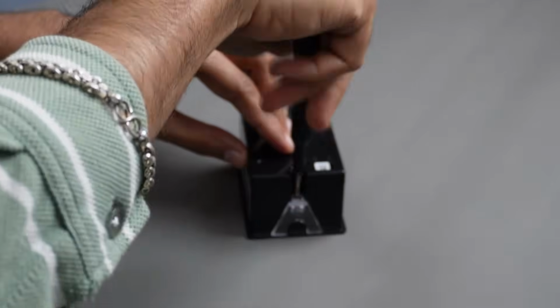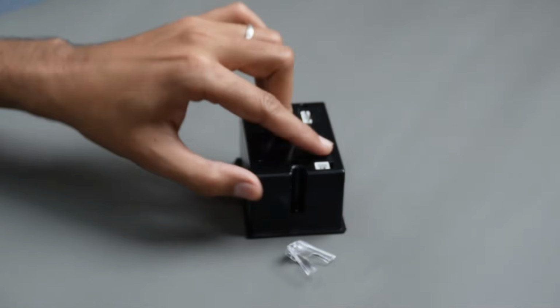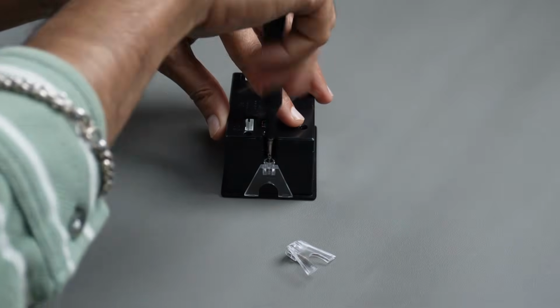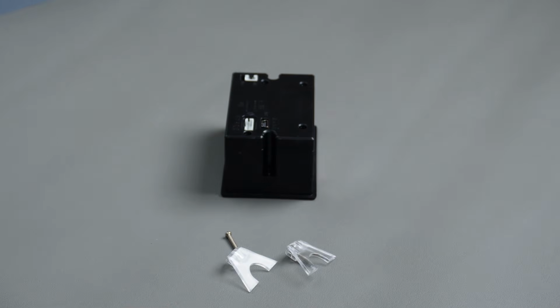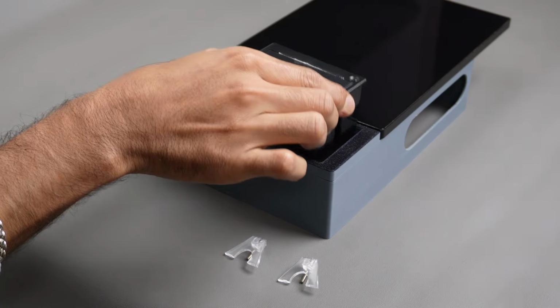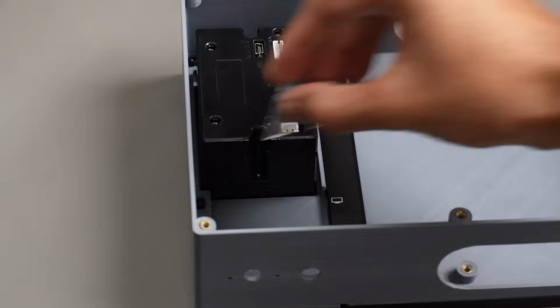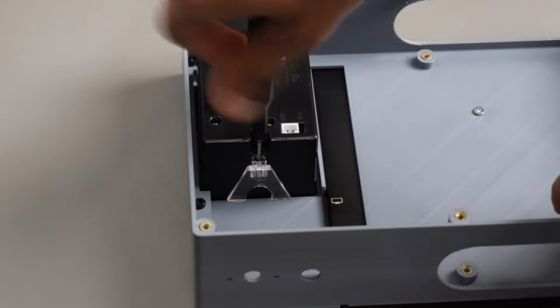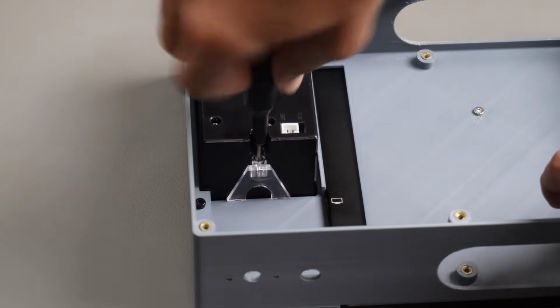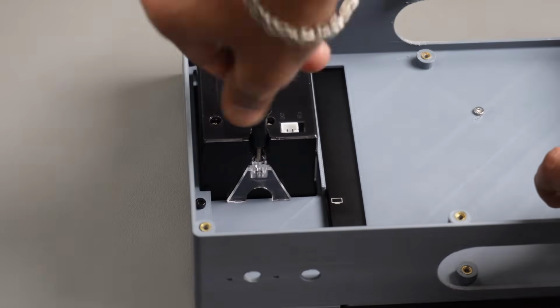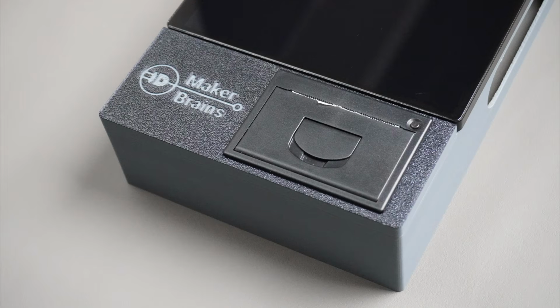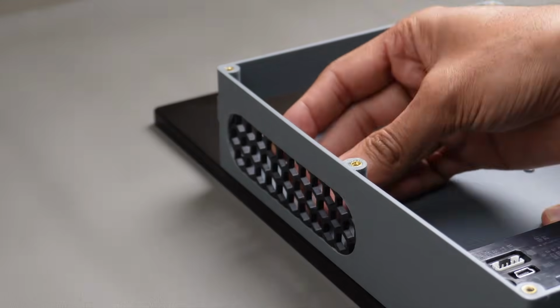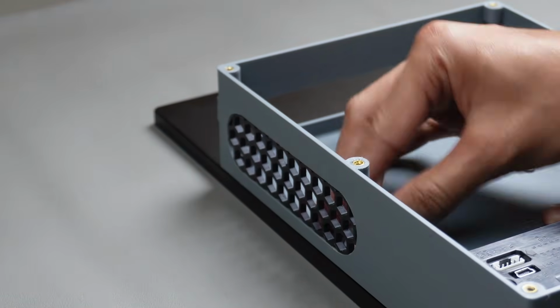Use a screwdriver to unscrew and detach both side mounting brackets. Insert the printer into the printer cover opening. Screw the clips back to secure the printer firmly to the housing. Take the two side vents and snap them into their respective slots.